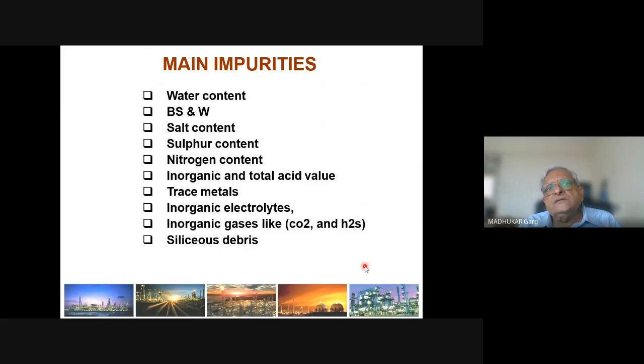So the ship fills up seawater in those compartments so that it has its stability, which is called ballast water. After emptying out the crude oil, it takes our seawater, the seawater on our shore, and it sails back to the Middle East. There it empties out the water and fills up crude oil. So that is how the salt gets into the crude oil, and also the water, as also the water which is associated with the crude oil in the well itself.